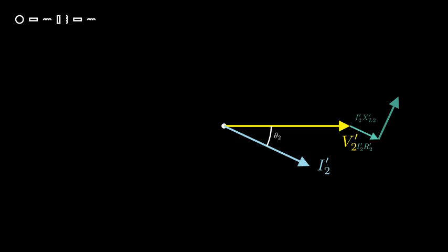Next, not all of the magnetic field created is useful. Some of it leaks and doesn't link with the other coil. This leakage acts like a small inductor. A voltage drop across an inductor always leads the current by 90 degrees.